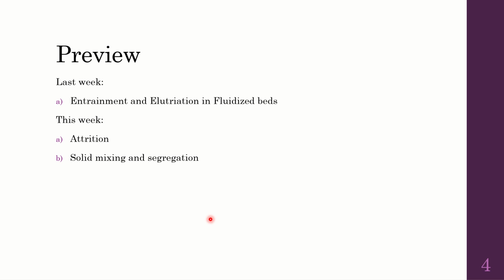there were 3 assumptions. The first assumption is that a fluidized bed is considered to have 3 distinct phases in the freeboard region. The first is the gas stream plus the dispersed solids. The next one is the agglomerated solids coming from the bed, which is moving up, and the next one is the agglomerates containing some wall layer of particles which is moving down. So we have 3 phases inside the freeboard region.